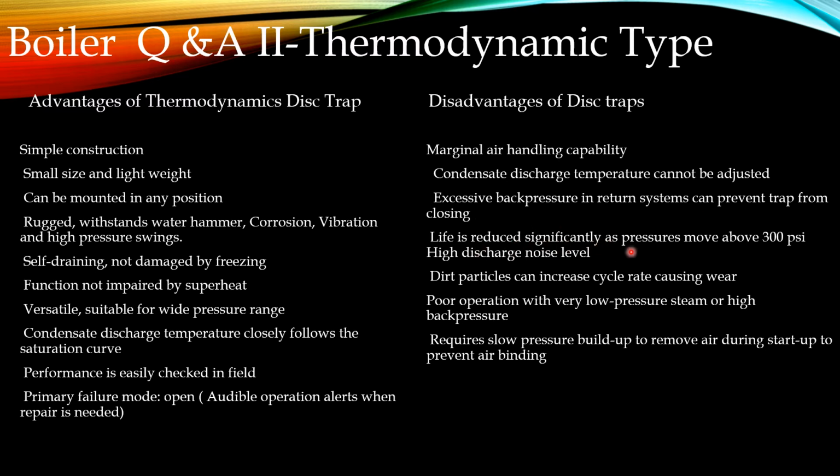Life is reduced significantly as pressure goes more above 300 psi, and high discharge noise level also will come. If the pressure is more above 300 psi, its life will reduce. Dirt particles can increase cycle rate causing wear. So if any dirt particle or foreign material is inside the steam, then that will damage the trap's inner area. It will wear and tear.